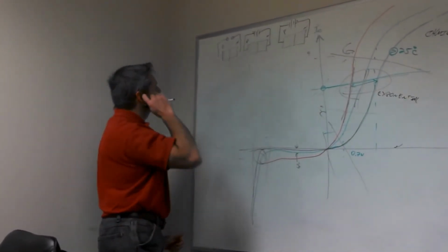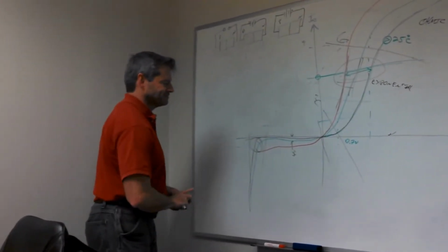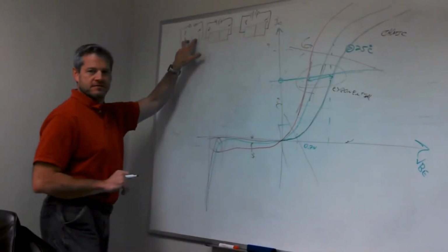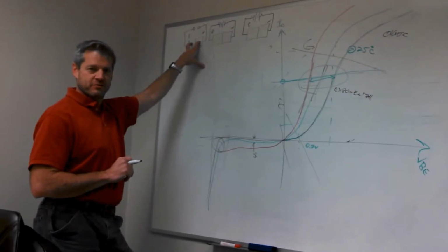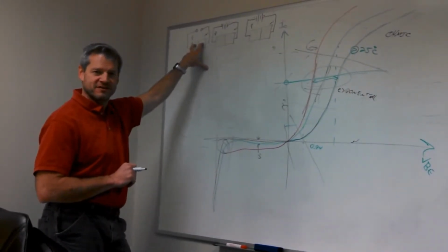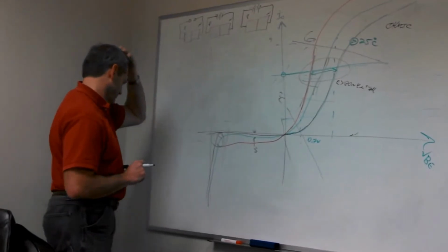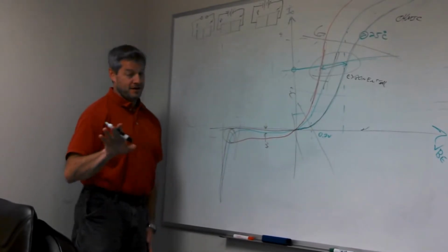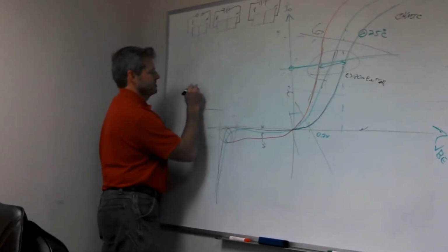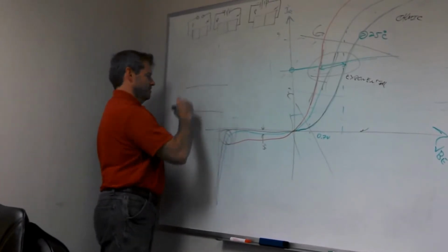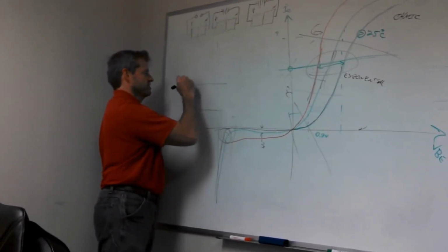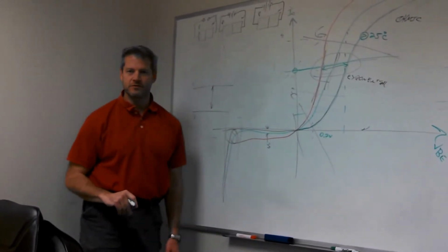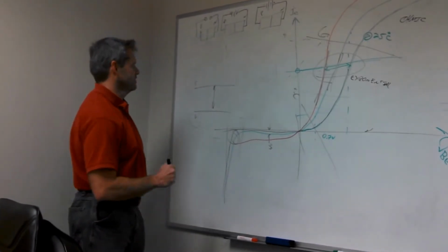Okay, so we know that this is silicon, which is a semiconductor, which is a crappy conductor, but it's sort of a crappy insulator too. When we add the doping, if I look at band gap drawings, I'm not real good at them, so pure silicon looks like this. This is your valence band, and this is your conduction band. And this is EG here, which for silicon is 1.12 or 1.2 electron volts, whatever it is.